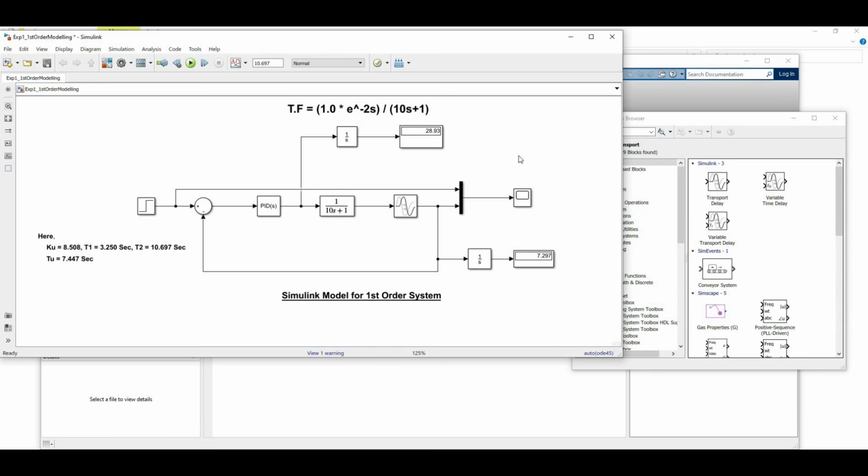So now the rest of the part is the calculation part. How to calculate by putting these values whatever we have determined from this Simulink model by observing the outputs. Just put the values on that formula, we will find out the parameters, right? And then we will compare whatever k we are getting, it is close to 1, exactly 1 or very much close to 1, it will be okay. Then theta, it should tend to 2, right? And tau, it should be around 1, very much closer to 1.